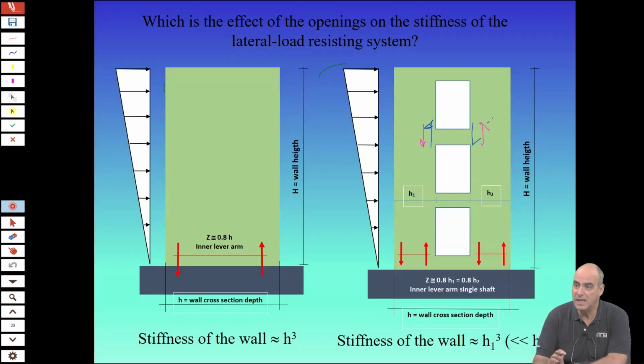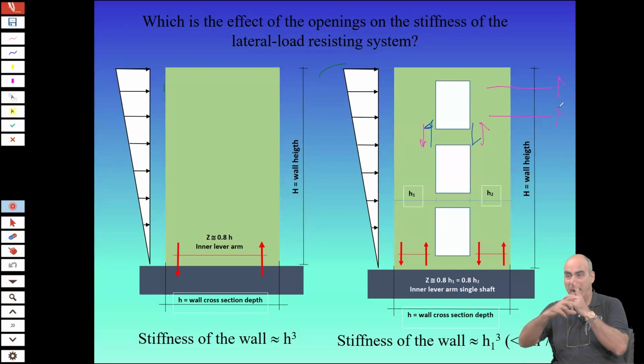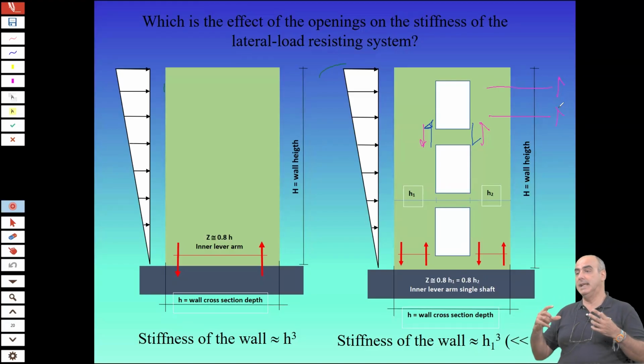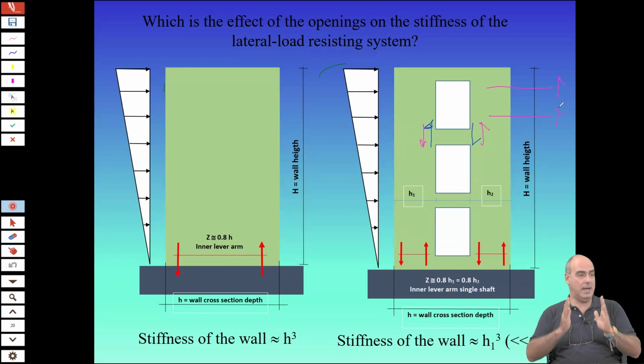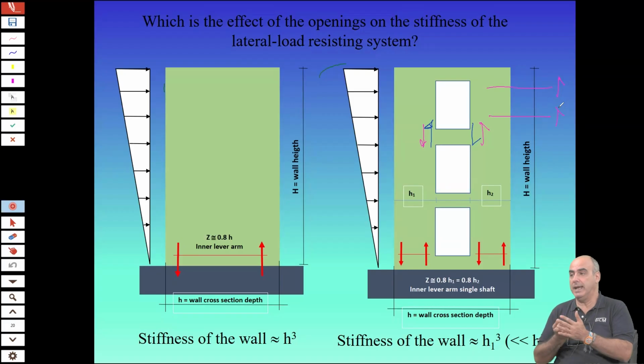Well, what if we put, it's possible, what if we put longitudinal reinforcement? How does a bar resist that force? Well, a bar resists that force basically, not merely through shear in the cross section. The cross section is small. It resists through dowel action. And dowel action means that the bar is pushing against the concrete. So at a certain point, you have cracking and crushing.